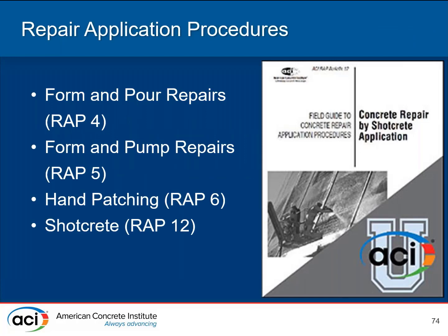move forward. I'm going to briefly touch on a couple of different repair processes, really how to get the concrete into the hole. And again, I want to refer you to these RAP documents, very, very useful. There's a lot of them. I'm going to try to focus on 4 of them that really are different ways you can get the concrete into the partial depth repair, the hole that you've created with your chipping hammers.